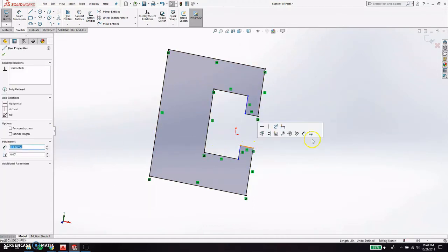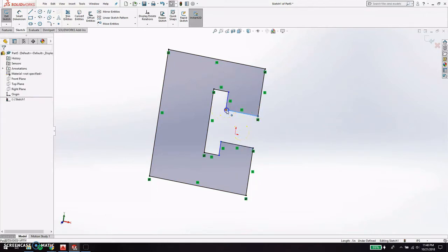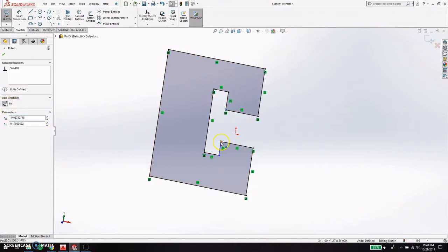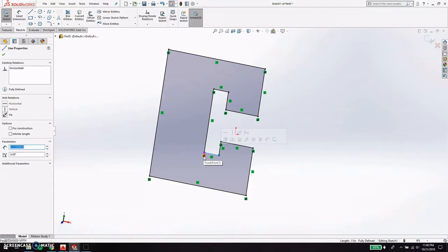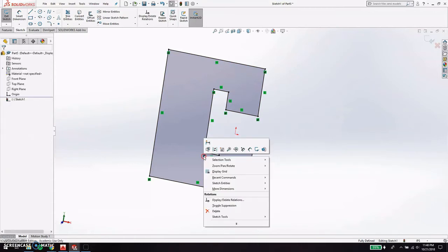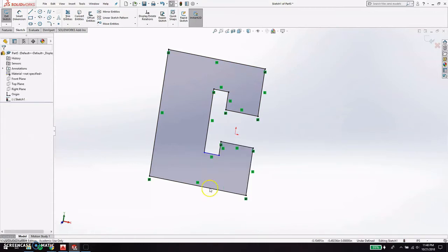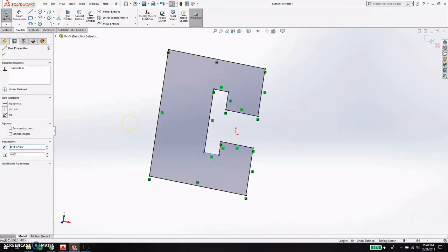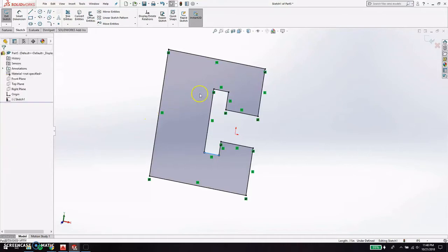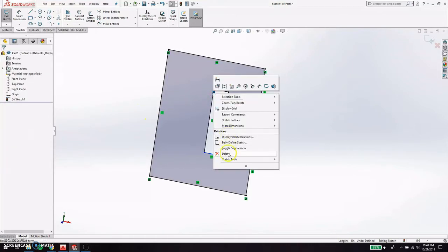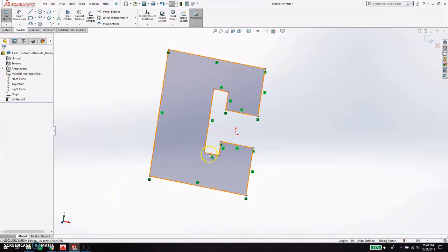And now this I'm going to make a quarter, and I'm going to make this a quarter as well. And I'm going to fix these points at the end to make sure they don't move. And I'm basically just going to do that for all of this stuff. So this point right here is fixed, but I'm actually going to delete this fixity so that I can have this thing move in this direction. I'm going to put this as 0.25. And that didn't work because this guy up here is fixed. So you start to get a sense for how to make everything work.